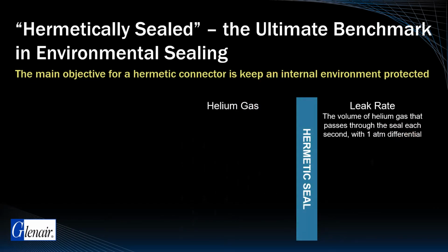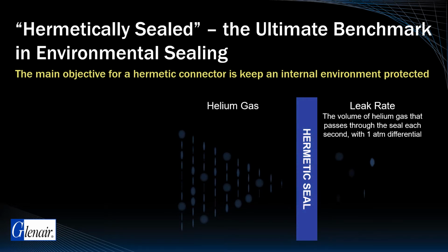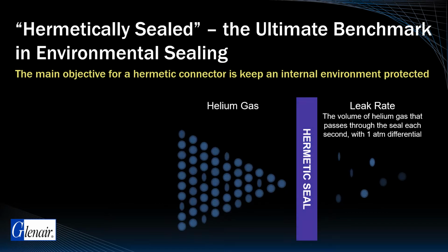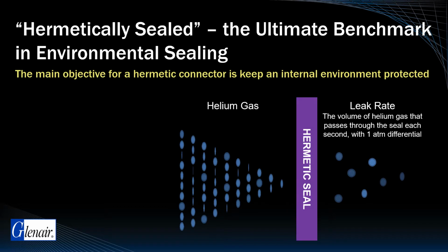As we said, hermeticity is a measure of airtightness. Helium leak rates are the methodology used in our industry to determine the exact degree of airtightness delivered by a particular hermetic device. The extent of any leak, or the degree to which connector materials and sealing methodologies still allow gas to pass through the hermetic seal, is referred to as the leak rate.